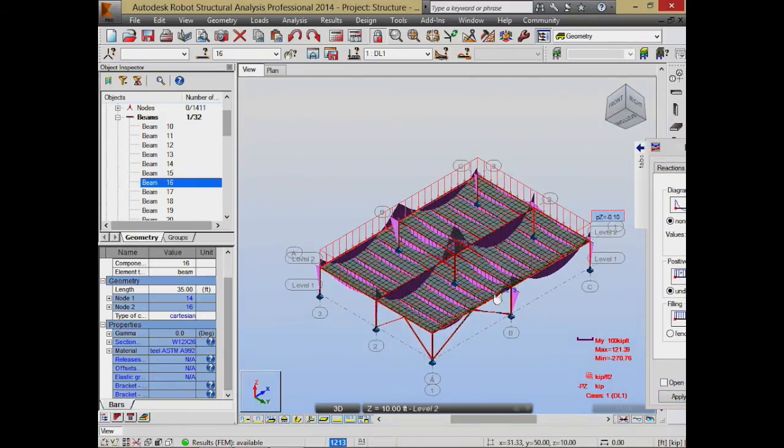Yeah. It actually has a bigger bending moment on that. That makes sense because loads are coming from both sides to that center line of beams. These ones on the edges aren't nearly as badly loaded. What's happening over here is interesting, there's definitely something funky going on. There's not so much shear and bending moment on those, and it has to do with those braces being there. Somehow that brace is shortening the spanning length quite a bit, so there's much less load over here than over there.